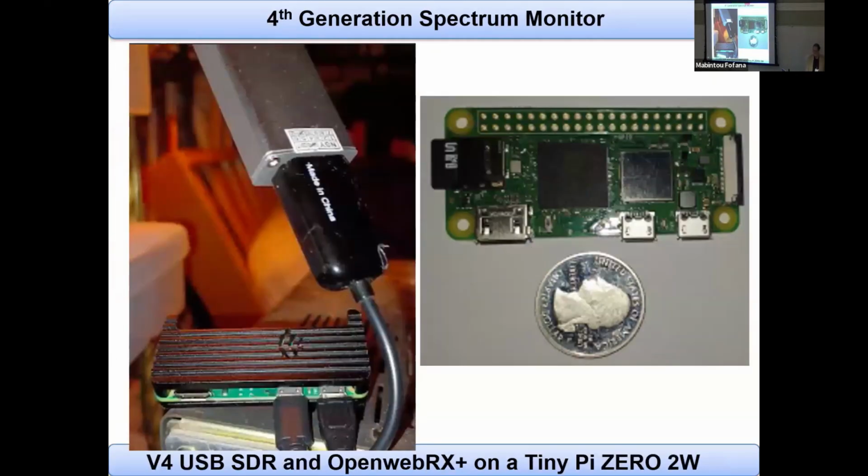I actually jumped it. 3.5, but so I had this working on a Raspberry Pi 3B, and working quite well. Now, this was a server. This is a Spectrum server, so meaning it's placed out of sight, could be out of sight, could be placed right on the antenna, 30 feet up. It can be in a proper weatherproof housing. I could supply voltage and I get a full Spectrum display that I reach with my browser on a wireless link on either Wi-Fi or Bluetooth link.